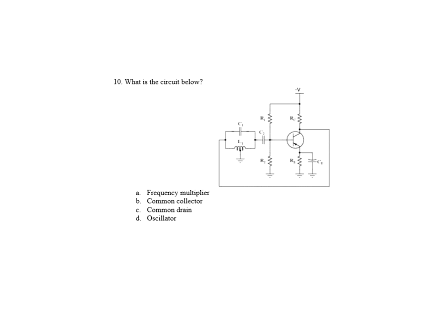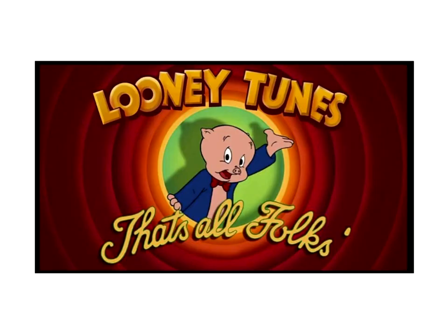All right, hey, what is this circuit below? Well, it's a common emitter amplifier. I can tell. It has your input on the base and the output off the collector. But look, it has a feedback loop on it coming from the output to the input. And what's in that feedback loop? Look, an LC tuned circuit. Now remember, we mentioned to you that tuned circuit might be over here in the feedback loop. It might be down here, so you have to watch. So what probably is this circuit? Most likely it's an oscillator because it has an LC circuit in its feedback loop.